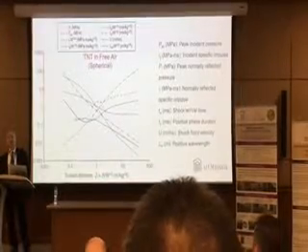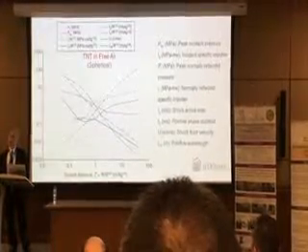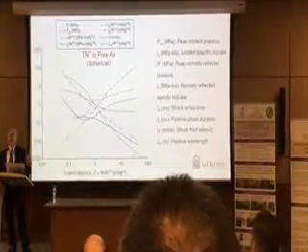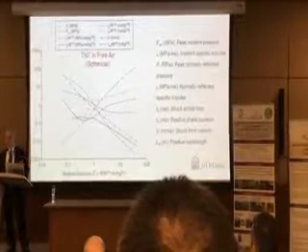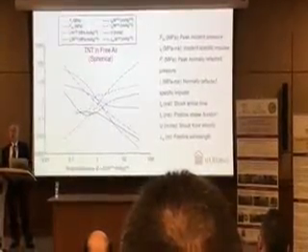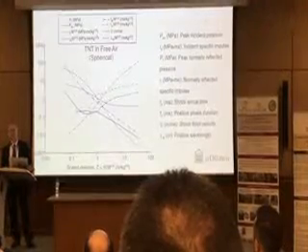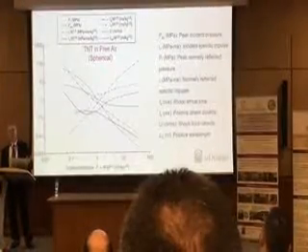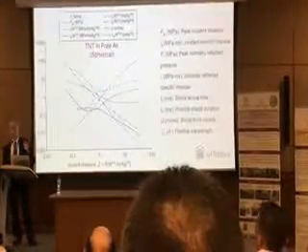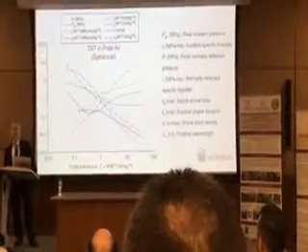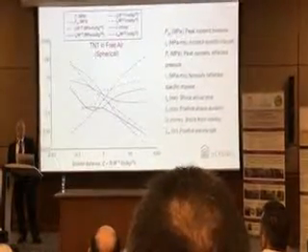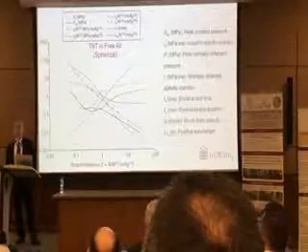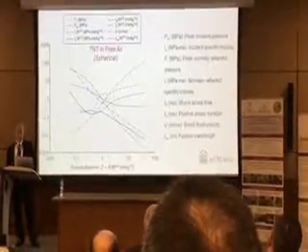They have done a lot of actual explosions, and they came up with empirical curves. So as you can see, these curves look very funny because there's no closed form equations behind them. They're just plotted as average values from their explosive tests. U.S. Army released this for the benefit of structural engineers, civilian engineers.